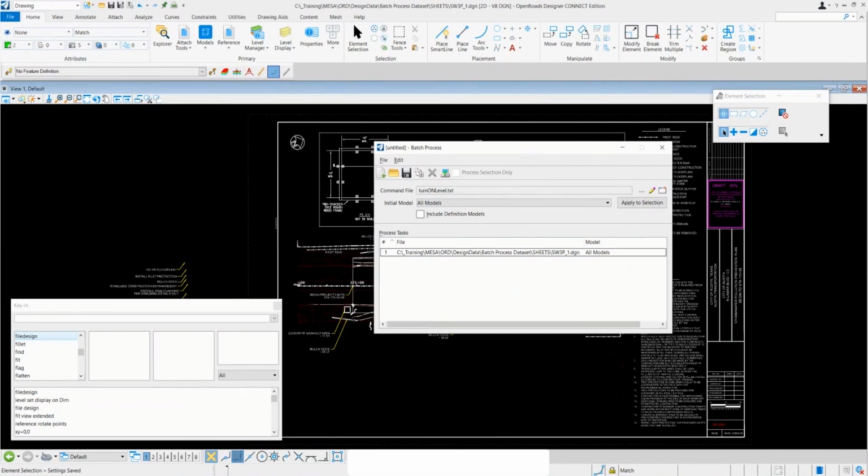And I did this on purpose because I do want to show you that if you click on the file name in here, you can swap out the name of the DGN with an asterisk so that it grabs all the DGNs in this folder. That way I don't have to go in and drag all of them. I can just set up this file name with the folder.